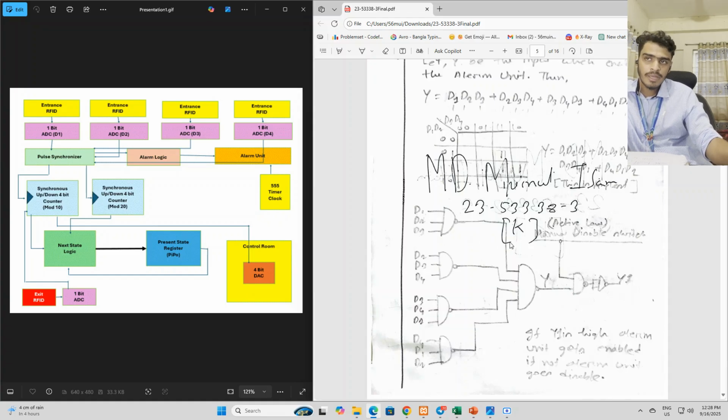And see, there is a manual disable switch, and this is an active low switch. If you press 0, that's the active mode of this button. The alarm is already triggered, right? We need to turn off the alarm, so that's why I placed the manual disable switch here.